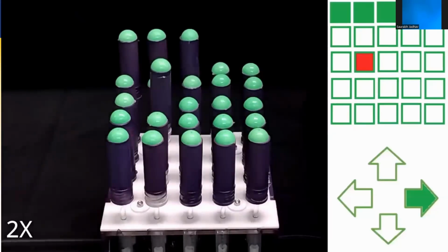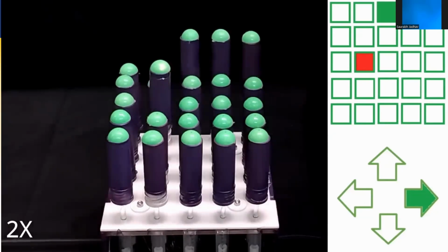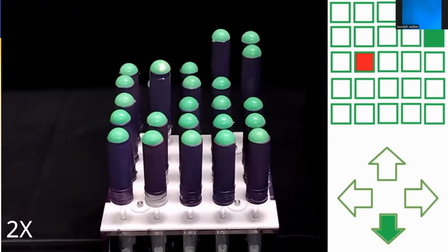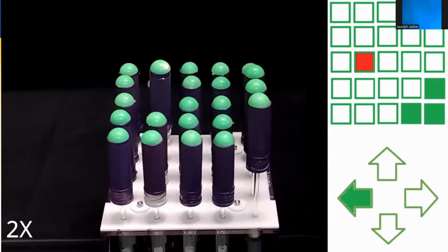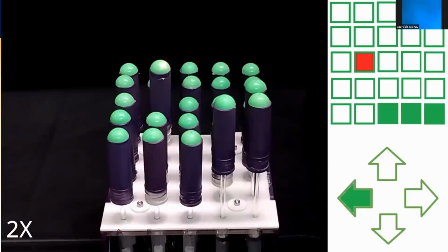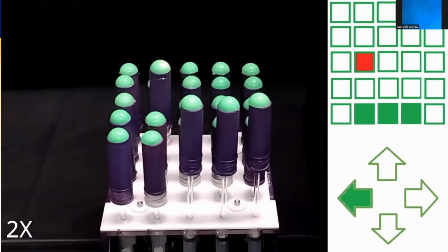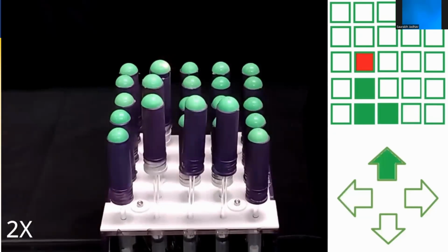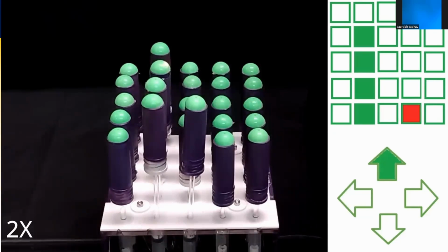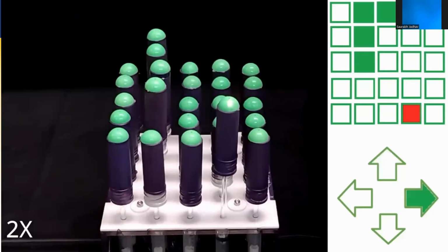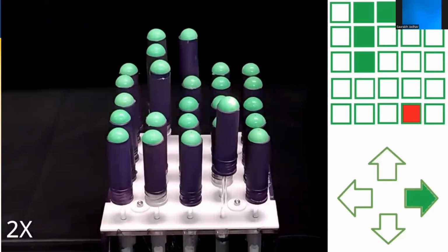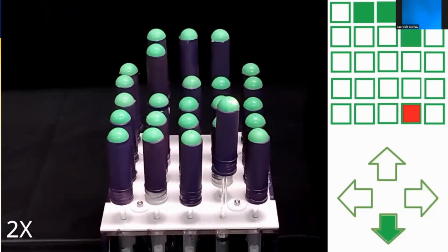We demonstrate the implementation of the fluidic matrix circuit for controlling a fluidically driven shape-changing display with 25 independent actuators. We control these 25 independent actuators using just 10 solenoid valves, 5 on the outlet and 5 on the inlet of the fluidic matrix circuits. The shape-changing display could render various shape patterns, including a variety of geometric shapes, numbers, graphics, incoming visual data, and many other plots. In addition, we demonstrate the shape-changing display rendering every frame of a snake game